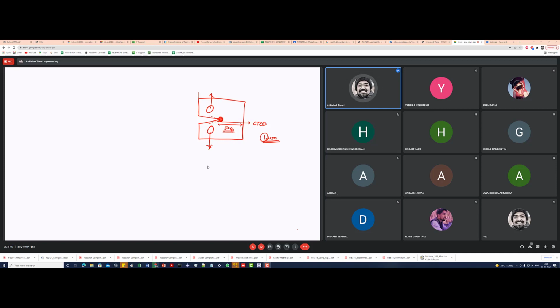So can we do a trick here? Can we do something about it so that we don't really have to model that many elements and we still can find out what we want to find out? We are going to entertain one of those tricks, which is called the modified boundary layer problem. That's just a fancy name for this, and sometimes it is also called the small scale yielding model.